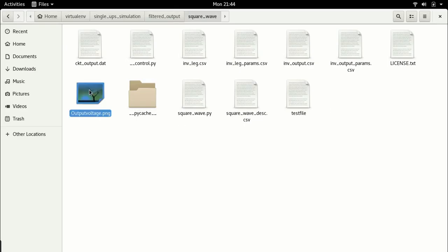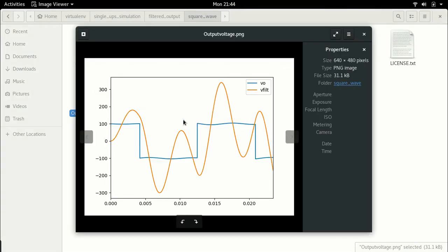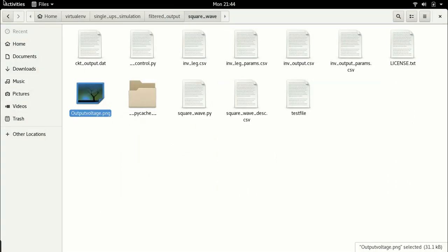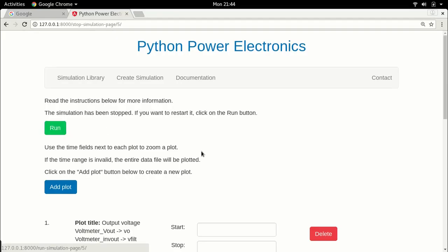Okay, something has happened. Let's click on this. So you see the oscillations have actually increased, but really what's happening is it is beginning to resemble a sinusoid. Now, what will you do here? We've increased the capacitor by a factor of 10. Let's now increase the inductor also by a factor of 10, because it's quite obvious that this is not enough.